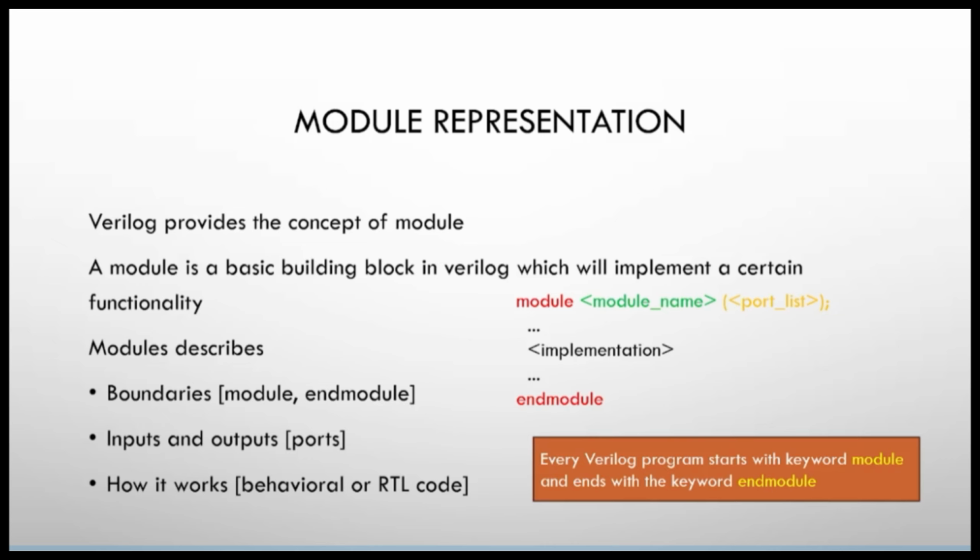So now we are going into the language. What does Verilog HDL actually consist of? As you already know, Verilog HDL is a programming language, right? Any program is built with some syntaxes and some properties, is it or not? So basically in Verilog, when you are building code, everything will be built within the module. So we can call these modules the basic building blocks. Why? Because whatever code you are writing in Verilog, you will be writing within module and end module.